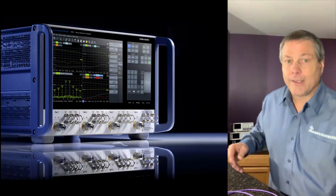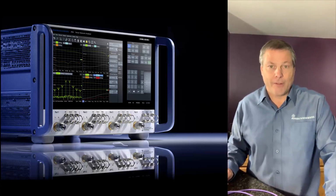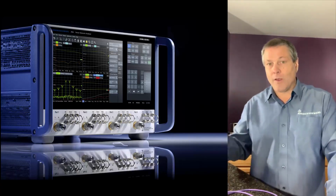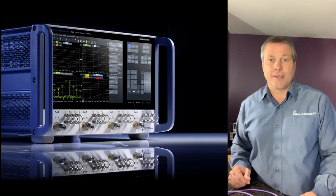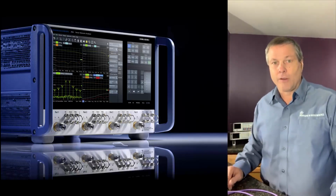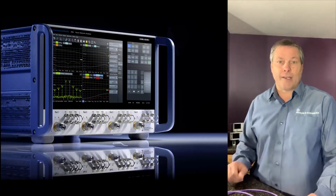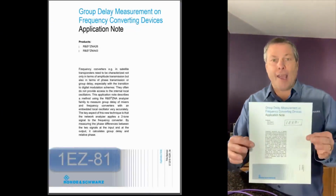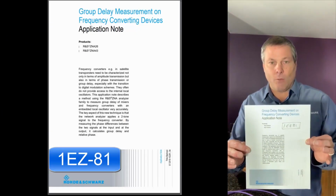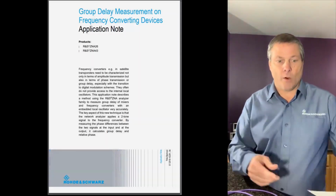Now, of course, in this series of videos, I'm using the Rohde and Schwarz ZNA vector network analyzer. This network analyzer was introduced about 1 year ago, and it has been optimized for making measurements on frequency converting devices like that MyTech satellite block down converter. So in particular, I'm going to use option K9. This is our two-tone technique, which we use to measure group delay on frequency converting devices. If you want more information on this option, you can refer to application note 1EZ81. This is on our website, and it goes into great detail about how the two-tone technique works for measuring group delay.